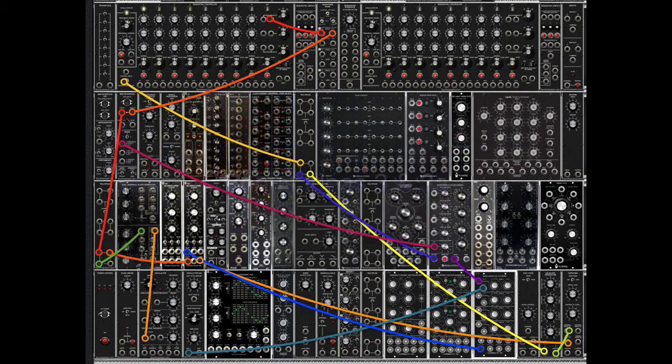Another idea, if you have your modulator in pulse, not square, but pulse, where the width has an effect, you could bring a modulation source into the pulse width modulation input. This is an LFO. If you set this to the lowest speed, roughly about halfway up, the 3 switches all the way up, middle, middle, off, off, middle, middle, all the way up. Come out of the amplitude jack into the pulse width jack.